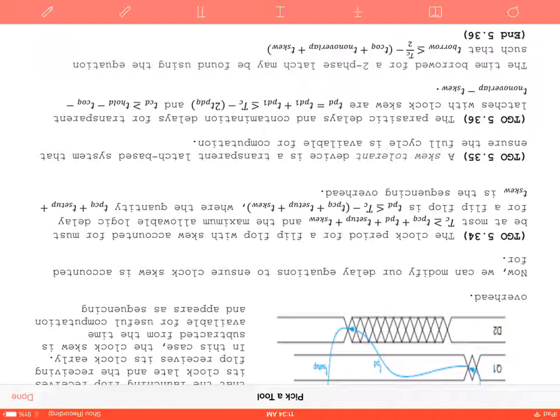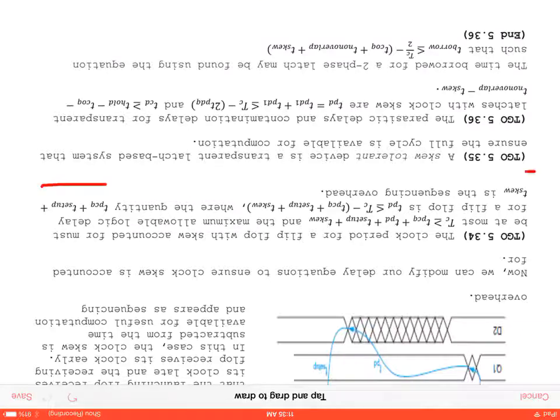Therefore, solving for the propagation delay, this means our maximal allowable delay is less than or equal to the cycle time minus that quantity TPCQ plus T setup plus T skew. And we've defined again TPCQ plus T setup plus T skew is our sequencing overhead. So the sequencing overhead is the difference between the combinational element and our sequential element. So recall that our flip-flop definition was just the same thing, except without time skew involved.